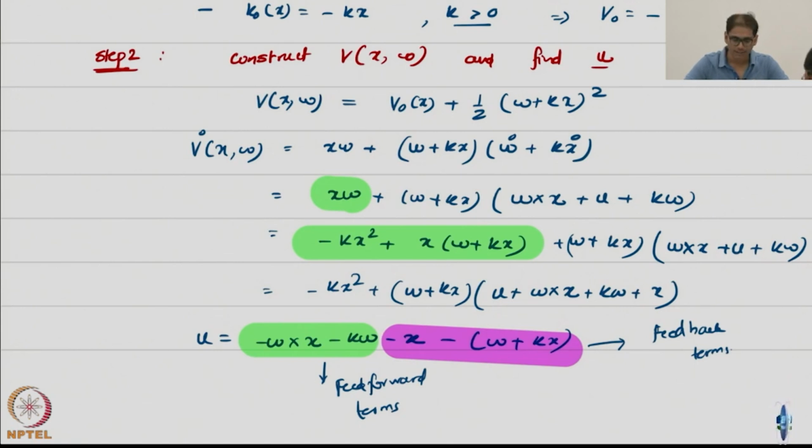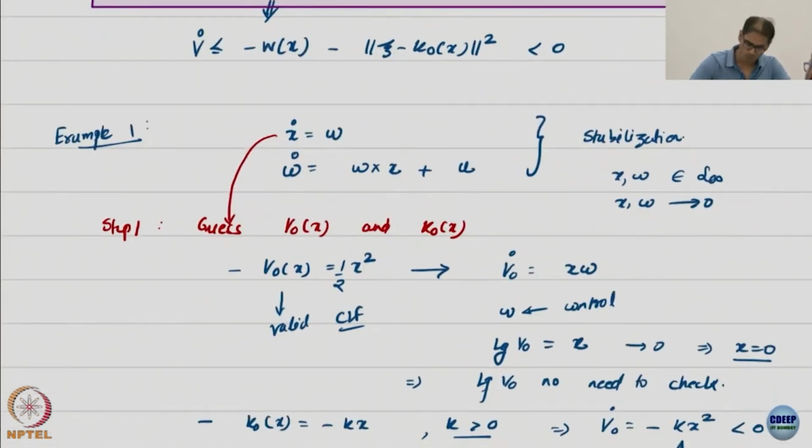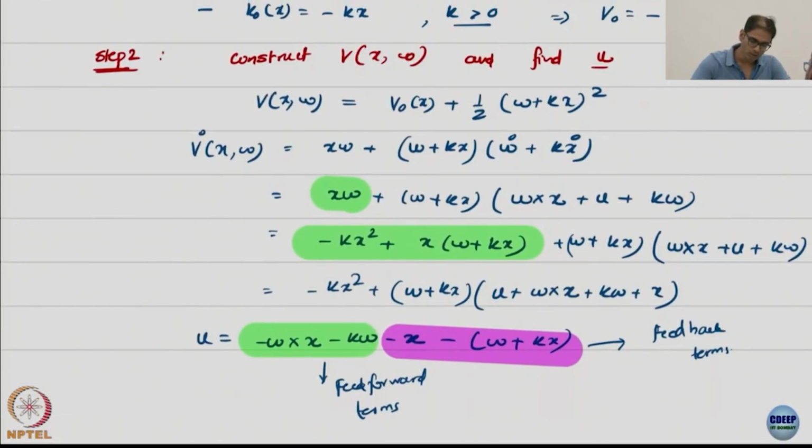And you can see again there is a lot of parallels here. Notice it's a nonlinear system, small nonlinearity, still a nonlinear system. But the control that you got is actually a PD control, because this is a proportional and a derivative. This is a proportional term and this is a derivative term. So if I again want to label more, this is the D term. So PD control.